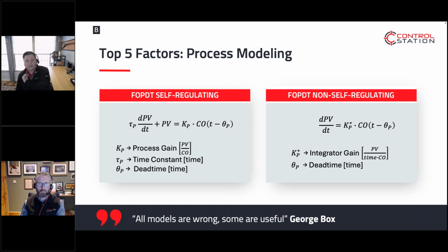And with non-self-regulating systems, with level controllers, we're looking at an integrator gain and dead time, which is kind of the integrator gain being a combination of the how far and how fast and delay. But these are all about characterizing the system. It's understanding the behavior of a system. We're applying some rigor to how we calculate the dynamics of the system. We're not trial and erroring it. We're trying to understand the behavior so we can get to the right answer.